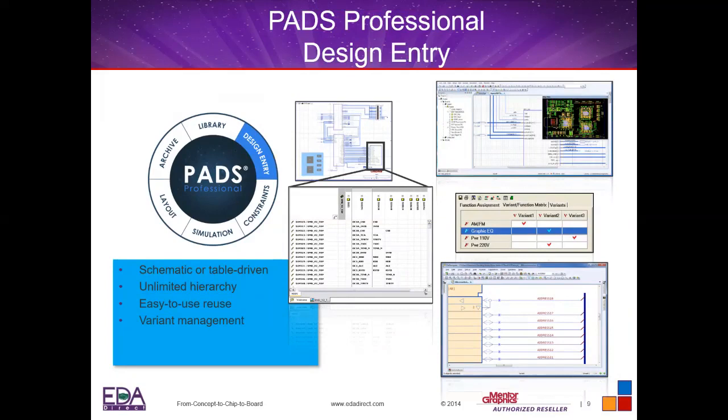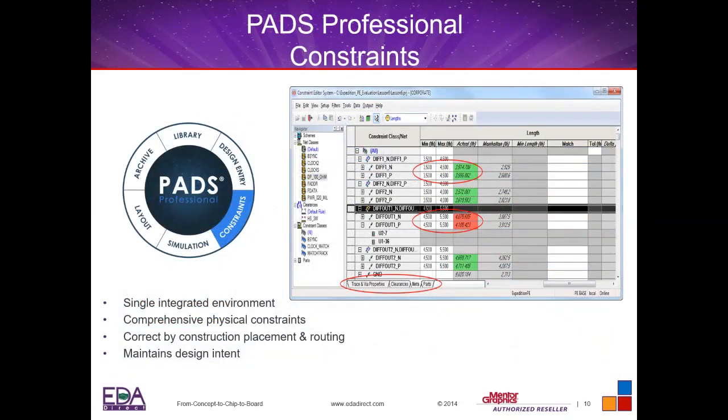For those of you that are designing one circuit board and you populate it different ways, we can manage all that in the schematic tools so that you have multiple BOMs and multiple schematics without having to manually take care of those things. You're also going to have constraint management tools that come with it. This is a little bit different than the PADS tool. It's all done through a single integrated environment in a nice little spreadsheet.